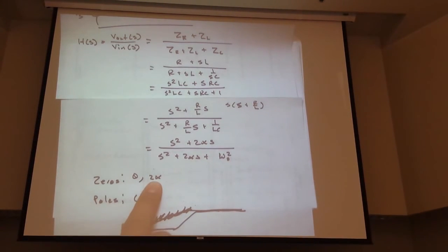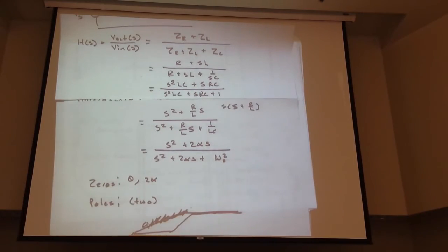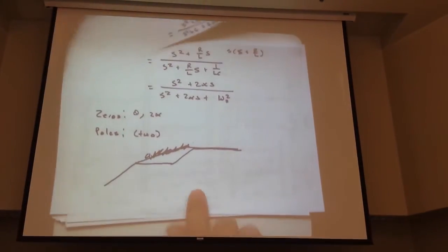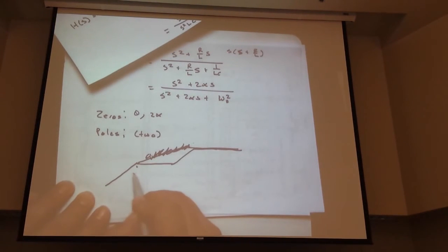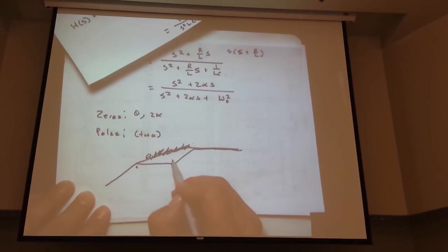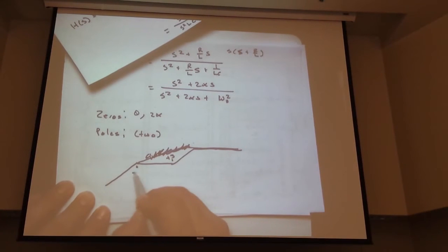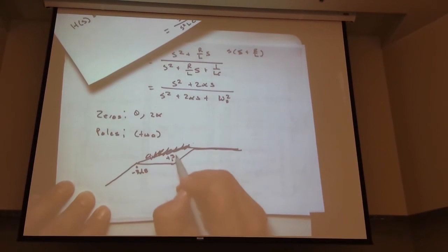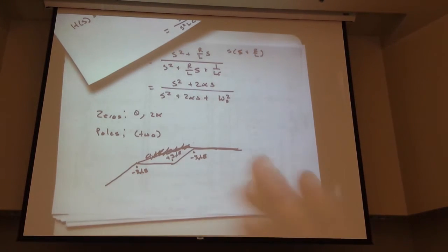So when we cross this 0, looking at the Bode plot that I scribbled on a little bit, we would have a minus 3 dB correction there, a plus 3 dB correction there, and then a minus 3 dB correction there. Those aren't absolute values, those are relative to the location of the straight line approximation.